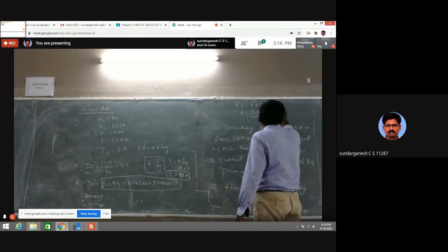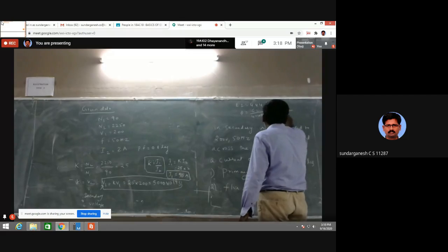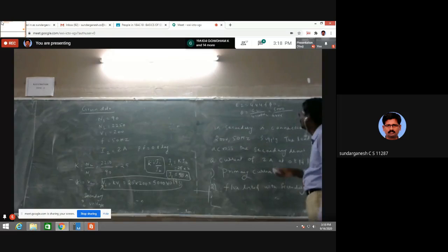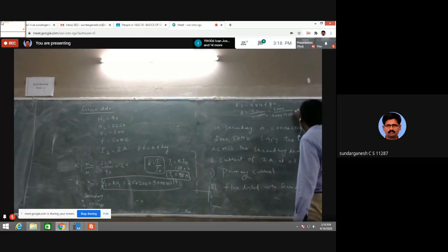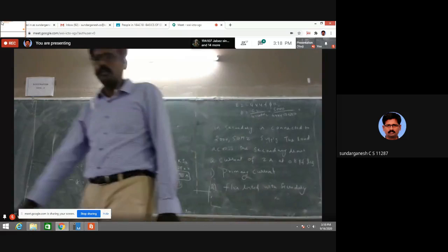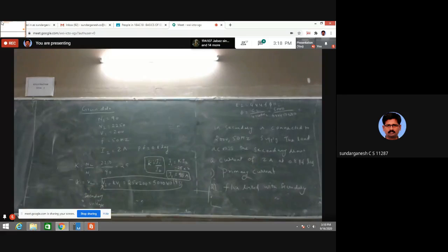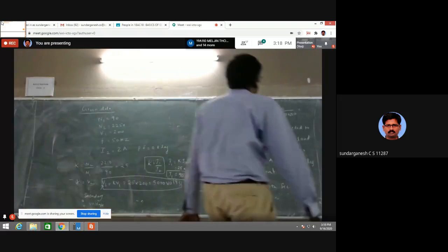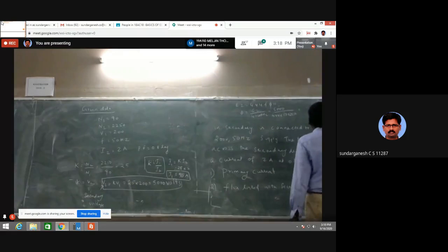So E2 is 5000, divided by 4.44, f is 50, N2 is also given, it is 2250. So the value of phi is 0.01 Weber.